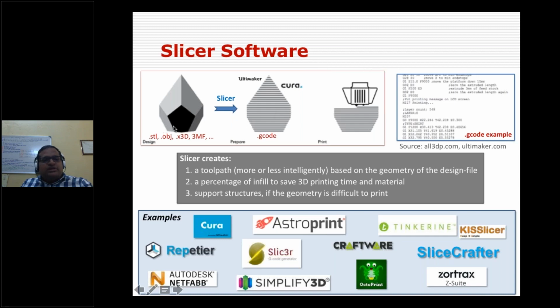So as we know, once we get this STL file, we need to slice it in order to generate the G code. The G code will be generated through this Cura software by giving the layer thickness. Say, I want to slice with 0.1 mm or 0.2 mm or 0.3 mm. So you just specify your layer thickness, and it's going to digitally slice it, and it will generate a G code, and you send that G code to the printer. So where it's going to happen here is the physical realization of this same G code.